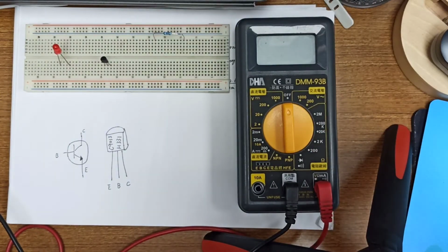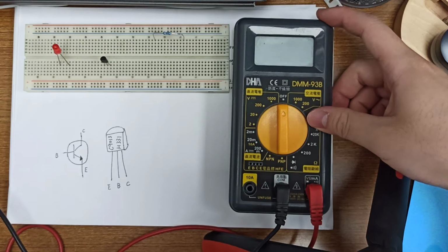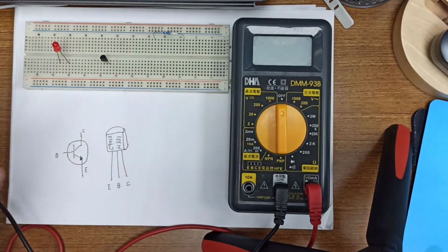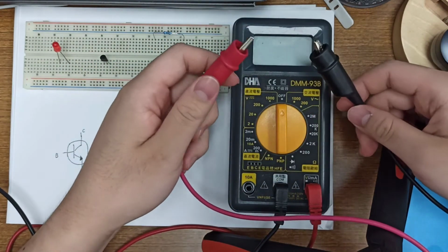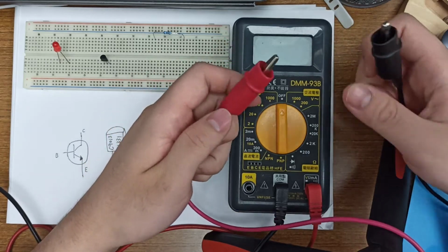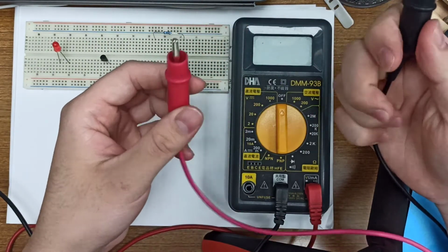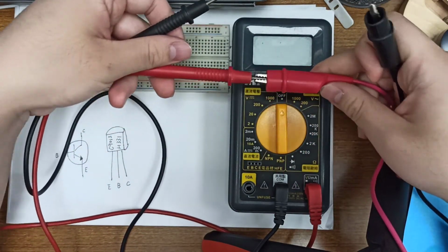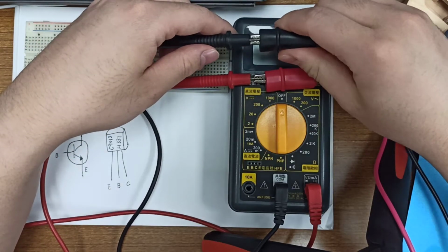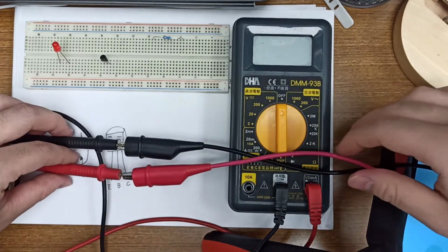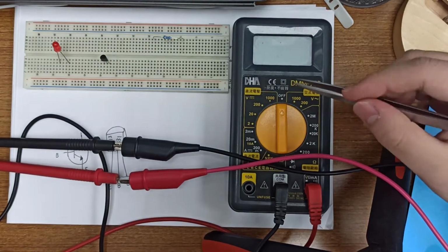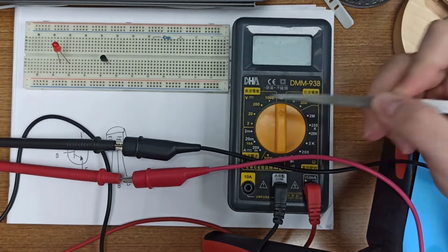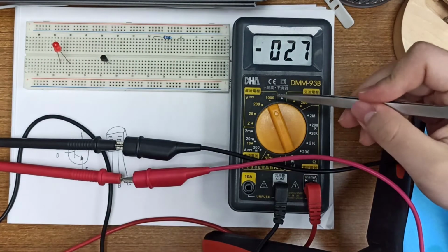Okay, next I will teach you how to measure the value. First I teach you how to measure the voltage. We're using the DC power supply to generate 5 volt to measure. This one is positive, this one negative. Using the multimeter probes to connect, positive to positive, negative to negative. So how should we choose the voltage level? The DC voltage level has 1000, 200, 20 and 2. First I show you if we choose the 1000 level.